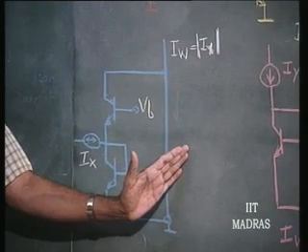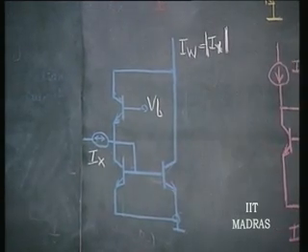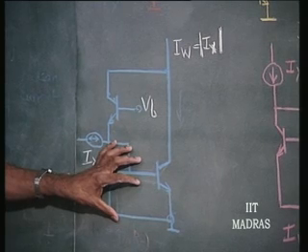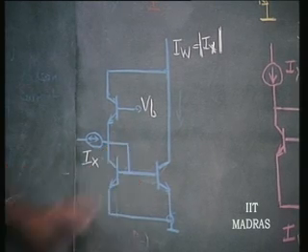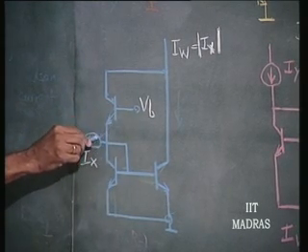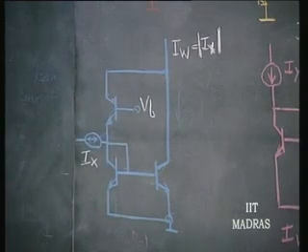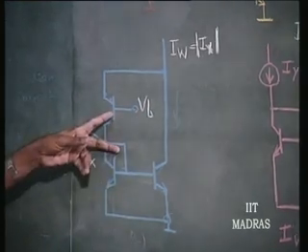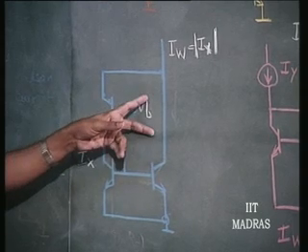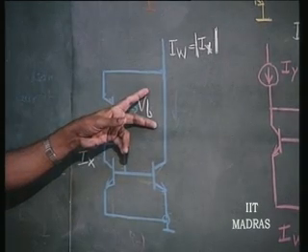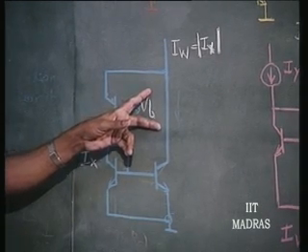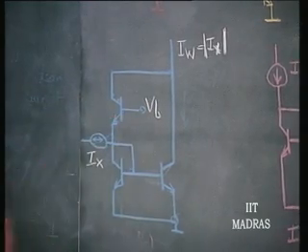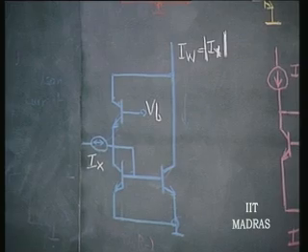Is this point understood? Now, what happens when the current is in the opposite direction? That is not permitted by this diode, it can be taken only by this, if this is biased properly. What do you mean by biased properly? The bias voltage should be nothing but 2 diode drops. If that is 2 diode drops, this is going to conduct properly, it should be just, let us say, less than 2 diode drops.